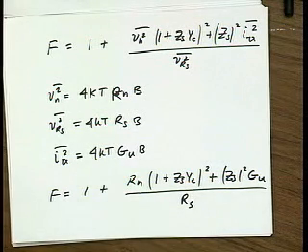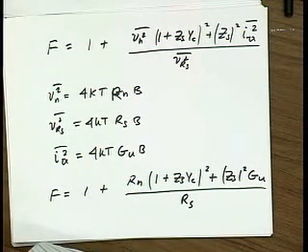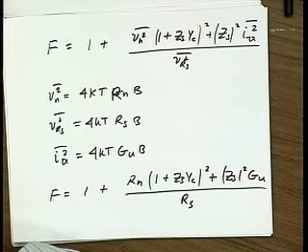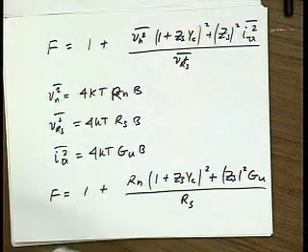The lower the noise figure. Yeah, basically, that was a good question that Kevin asked a couple lectures ago: why does the expression not work when RS goes to 0? When RS is equal to 0, there is no source noise. A noise figure is a measure of how much noise you're adding in addition to the source. So if there is no source noise, noise figure doesn't really make sense, right? Because no matter how much noise you add, you get a noise figure of infinity.